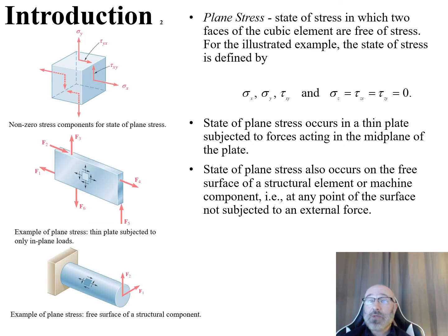So as we continue on with our introduction here, I want to now take a look at plane stress. So what is plane stress? Well, plane stress is a state of stress in which two faces of the cubic element, so two of the different faces of the cubic element, are going to be free of stress. So let's take a look at this illustrated example over here on the left right there. We have non-zero stress components for the state of plane stress right here.